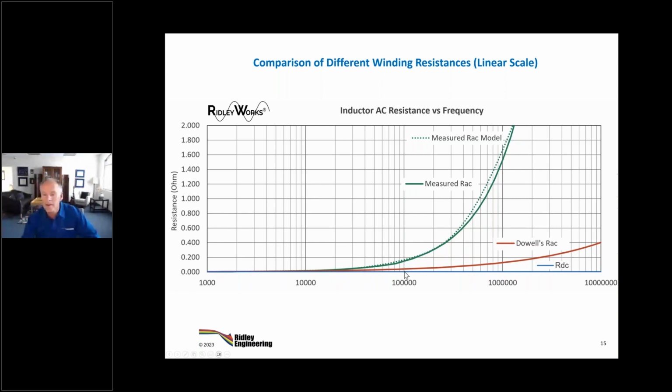Look how much we've increased this resistance here. It's gone from 2 milliohms to, I can't remember what that was, 60 milliohms or so. Now we're bumping that up to about 120, 130 milliohms. So we've got a lot more resistance coming in here. And then at 200 kilohertz, of course, it's separated even more. You can see the separation very nicely on the linear plot, but we can't read this down here. Same problem as the Coilcraft data that they presented.